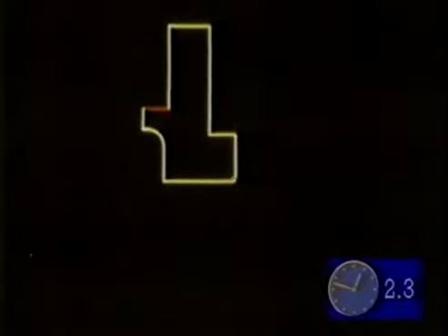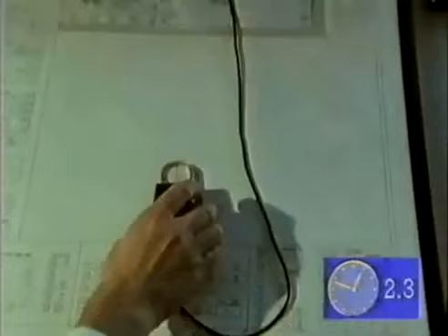But this is only half of the section. Because the gearbox cover Alan is drawing is bilaterally symmetrical, the computer can perform a reflection transformation and mirror the other half below. To do this, the completed outline to be copied is isolated, reduced, and the construction lines replaced. Alan then locates the center line, which tells the system where to mirror the outline he's drawn. He then puts the system into copy mode, and the other half of the image appears below.